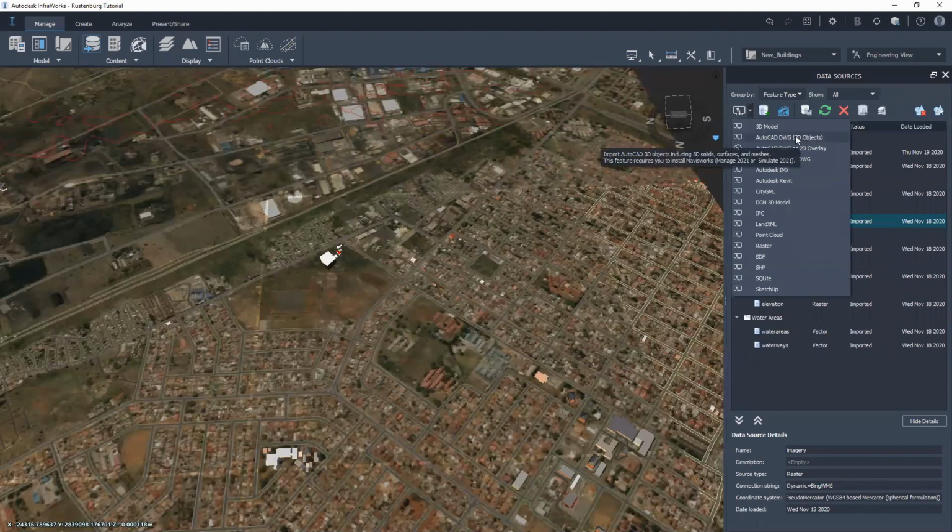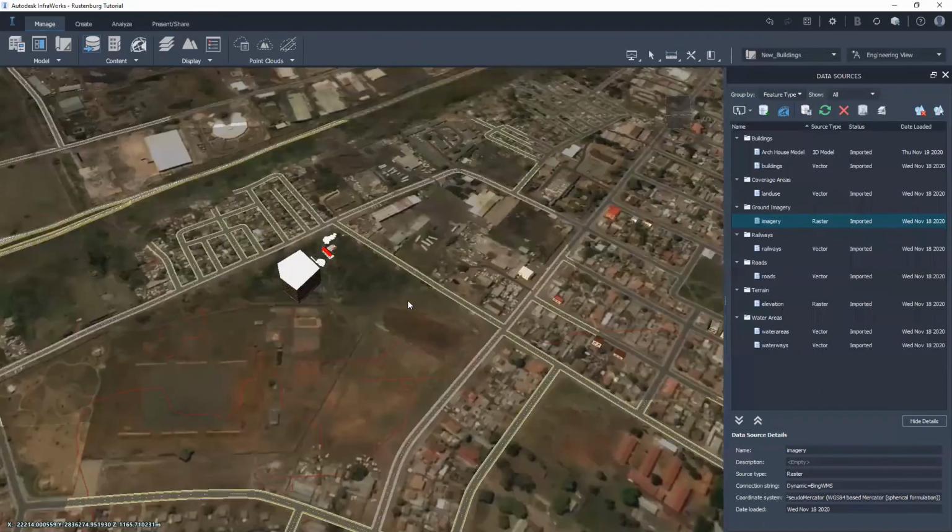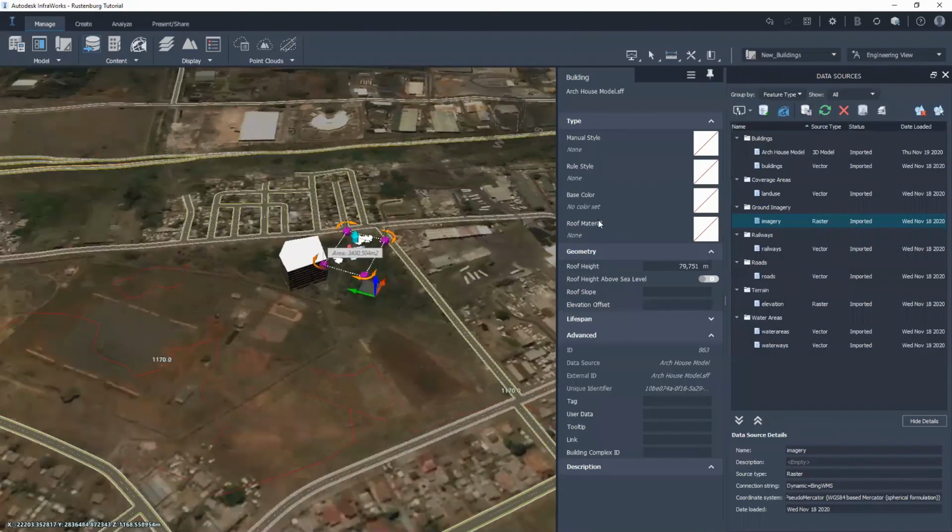I have not played around with this much, but I think you should also be able to set that property within the, let's look at this, base color, full style. Okay, so with Revit models, it does not look like you can do a transparency edit within Infraworks itself. I think it would have to be set up like that within your model that you import.